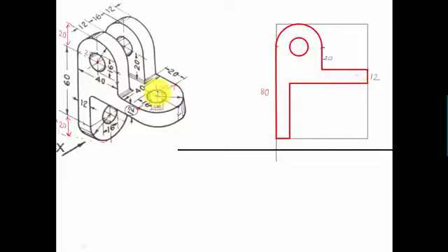Now guys, this particular point appears at a distance of 20 millimeters from over here. So from over here I'm going to be making an axis at a distance of 20 millimeters with the help of these so-called dash dot lines. Now this distance I'm talking about, since this circle has a diameter of 16, this distance is going to be 8 millimeters. So towards the right I'm going to be having a hidden line, something like this, and towards the left again a hidden line. There you go.